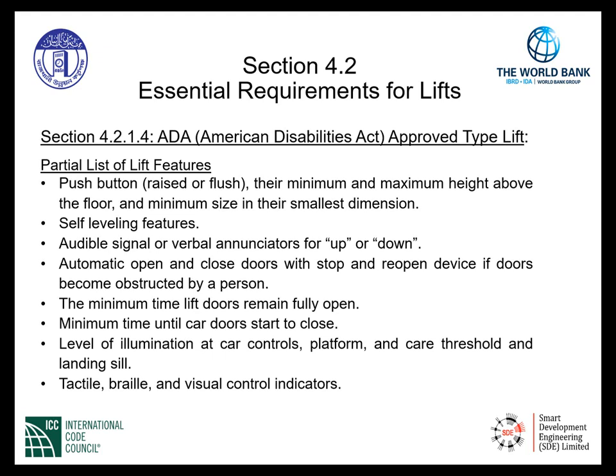Self-leveling features are indicated, as well as audible signal or verbal enunciators for up or down, indicating automatic open and close doors with stop and reopen devices if doors become obstructed by a person, as well as the minimum time lift doors remain fully open, and the minimum time until the car doors start to close.